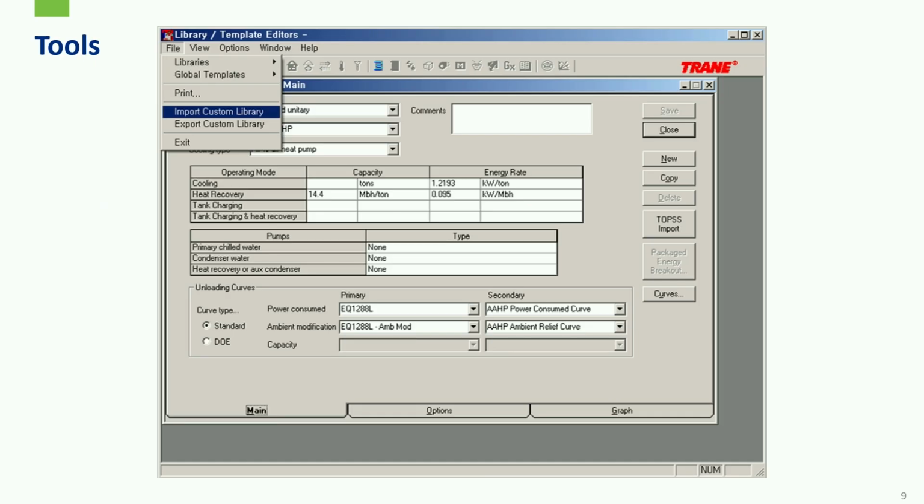So, a couple of quick tools. You're going to want to use something like TRACE, and you can pick any building energy modeling software. I just happen to pick one. But getting a really strong building energy model becomes the basis for the entire project. Whether you're talking about a standalone building or a network system, the model is ultimately what the design effectiveness is going to boil down to. So the strength of your model is what the whole house gets built on.